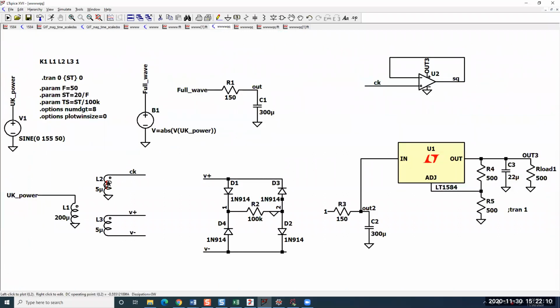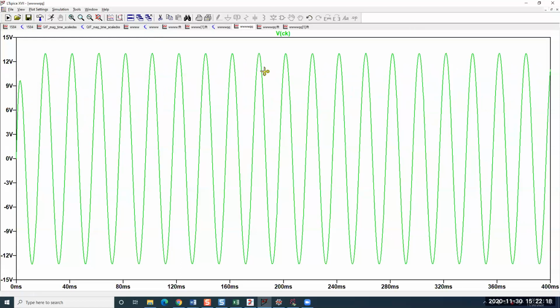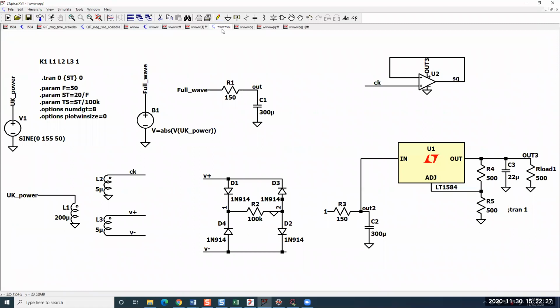if I have another side of the transformer, we call it conveniently clock, right? Well, now I got a sine wave, right? And so now if I just pass that sine wave into a buffer, here's output here, 2.7 volts to ground, I'm basically having a sine wave that's too big, and so it'll stay zero when it's less than zero and stay the power supply voltage when it's greater than the power supply voltage.